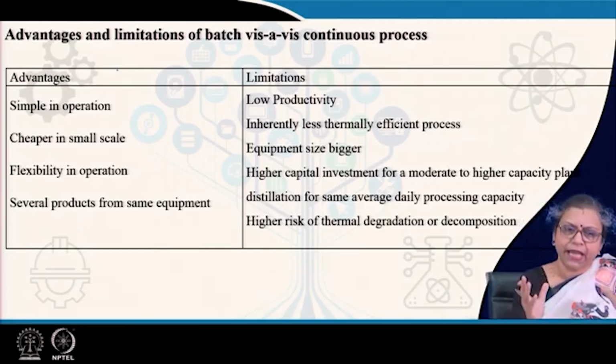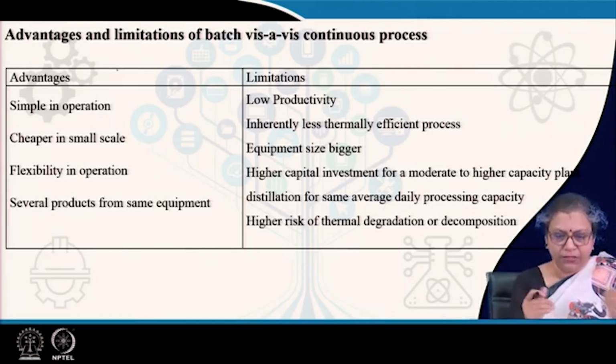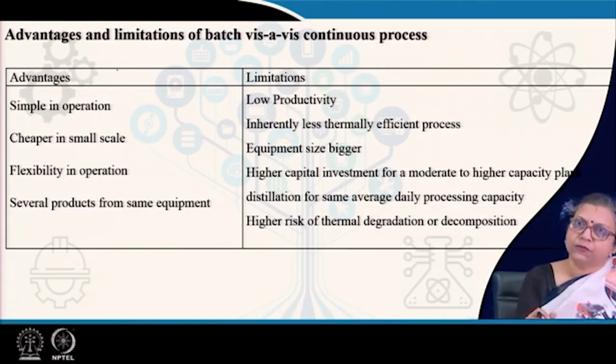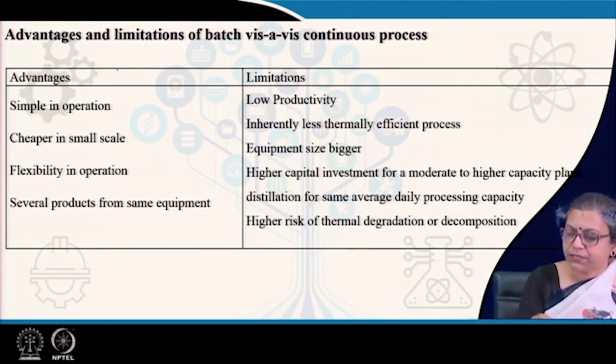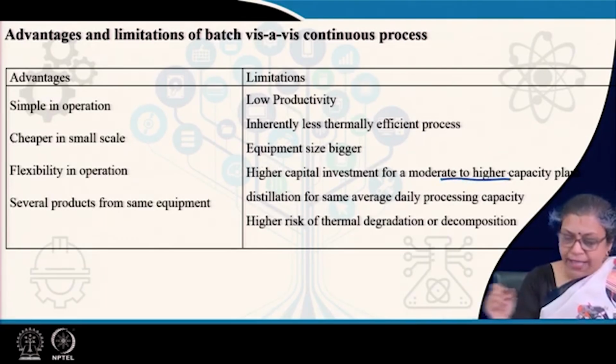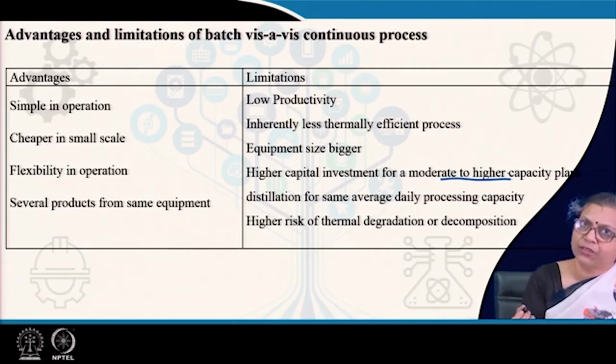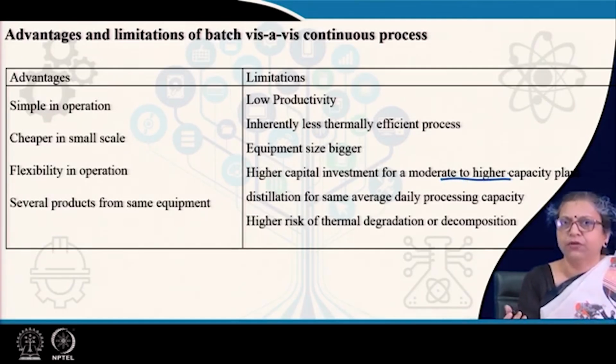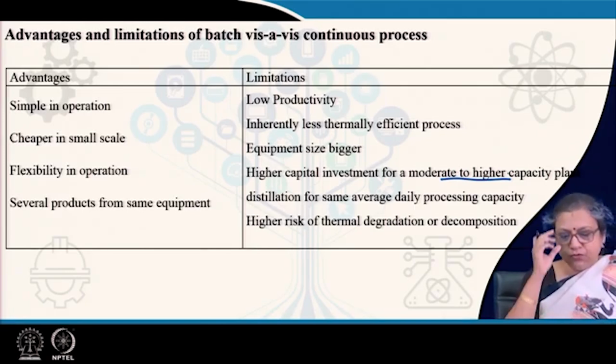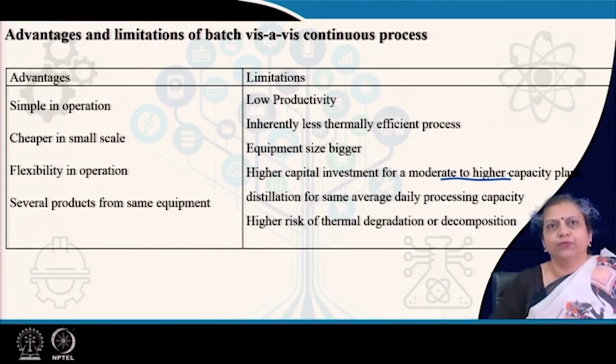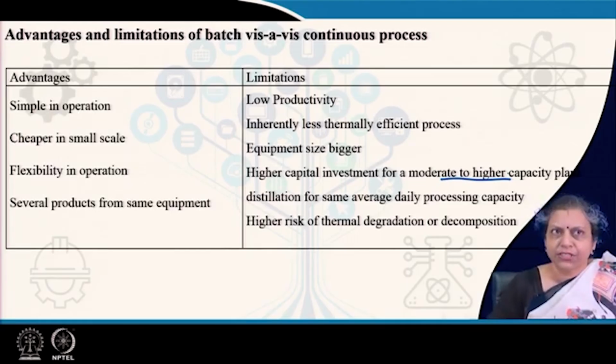Why? Because the entire feed has to be fed in the still itself, and then the operation has to start. So, for a smaller scale it is definitely cheaper, but this does not apply when we go for a moderate or high capacity plant. Flexibility in operation we have already discussed quite naturally, because you can use the same still for different variations, or rather for different compositions of the feed. You can also use this for different compositions when different product specifications are required, and from the same equipment you